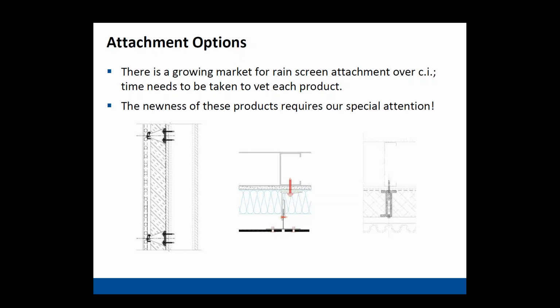I couldn't agree more. We've looked at it in a situation where we've even gone so far, because it's not just MCM, but there's other thin panels out there that can be installed with MCM on the same kind of clip system. We've gone to the point of creating a rain screen specification system so that from the air weather barrier out is all the same contractor's responsibility. Otherwise, every time you get multiple contractors coming into one place, you get the finger pointing when things go wrong. Well, that was his, I thought he was going to do that. And next thing you know, you've got trouble again. So I think Zeke is totally on it when he talks about making sure the fabricator can follow through on that.